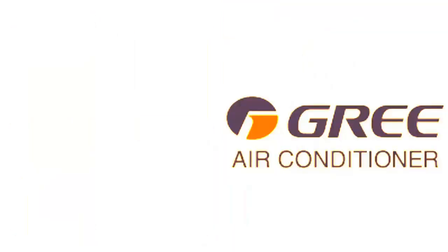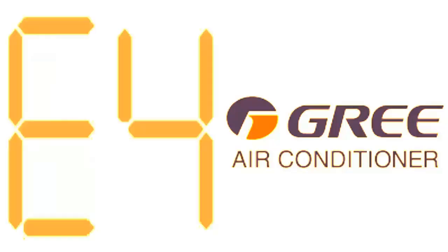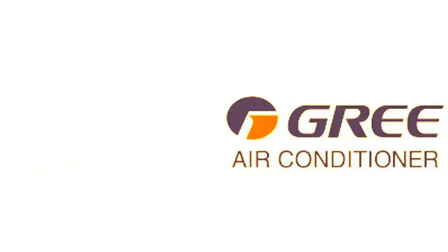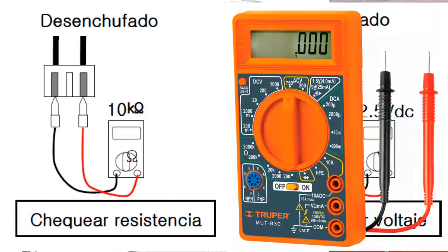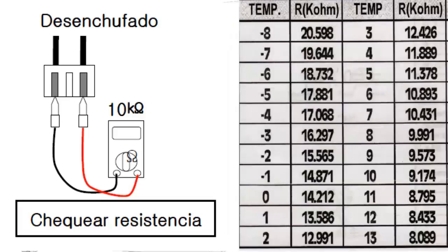Since many Gree units use temperature sensors to trigger the aforementioned error codes, we will quickly explain a procedure to test them effectively. Temperature sensor test. Disconnect the sensors and measure their resistance in kiloohms with a multimeter. The resistance should not be zero or infinite, and should decrease when rubbing the sensor with your hand. Compare the values with the manufacturer's specifications.